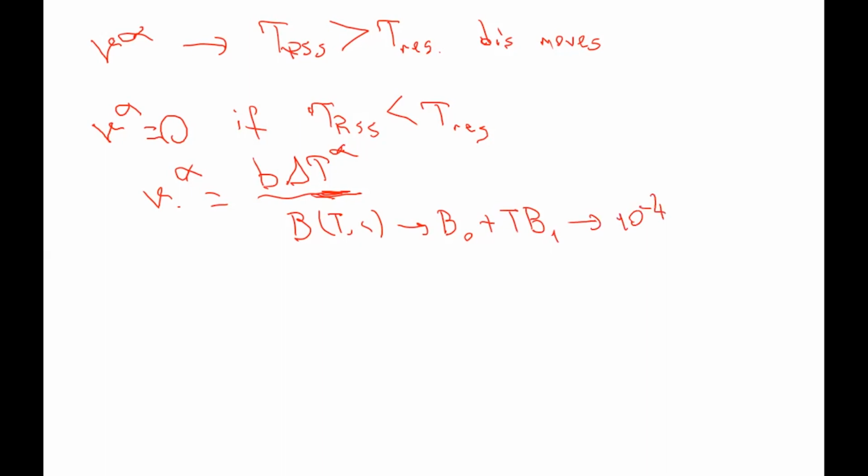All right. How about the excess stress? How can we calculate this value? What is the excess stress? The excess stress, delta tau alpha, is the resolved shear stress on each slip system minus, we need to subtract, the resistance of the glide plane, right?